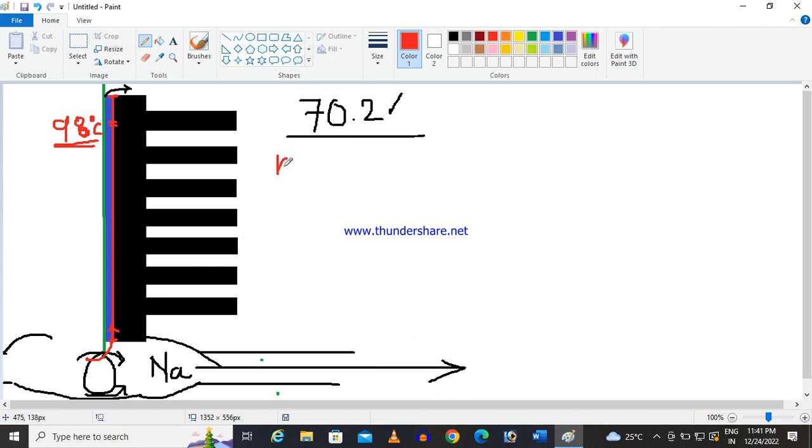So conduction depends on the thermal conductivity of the fin material, which is more or less constant, okay, in Fourier's law. But in Newton's law of cooling, h, which is the convective heat transfer coefficient, is basically a function of temperature and flow.